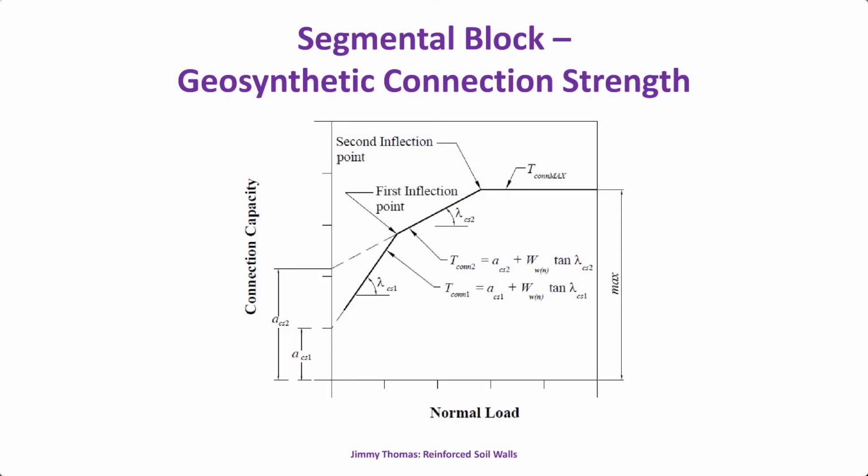Then finally, in the methodology, the actual result will be a curve, and we linearize it into segments. Then we can put a formula to that. If it is in this zone, I take this formula; if it is in this zone, I take this formula. There will be an equivalent apparent intercept. We don't want to call it a cohesion. It doesn't mean there is a cohesion there; it comes from the curvature. So basically we are doing curve fitting with some parameters. This we can put in the calculation method.